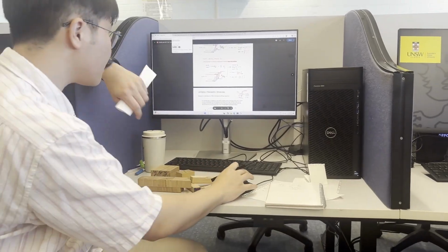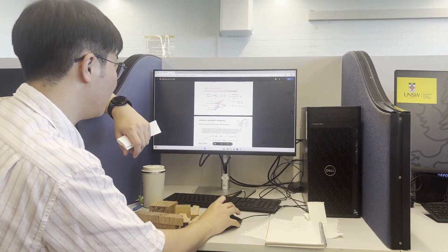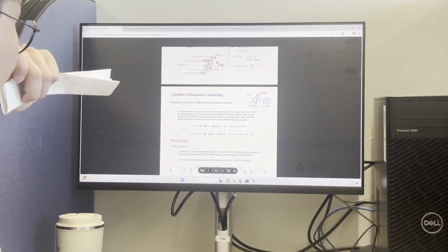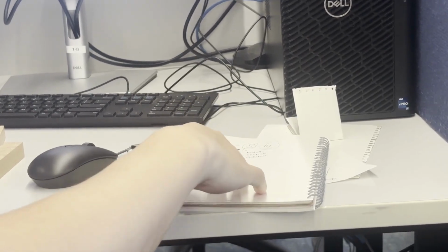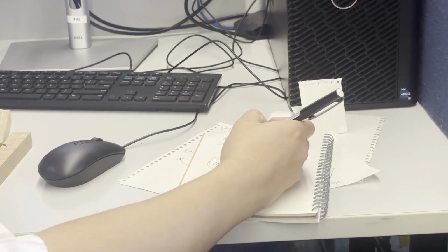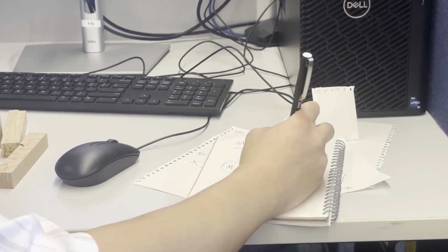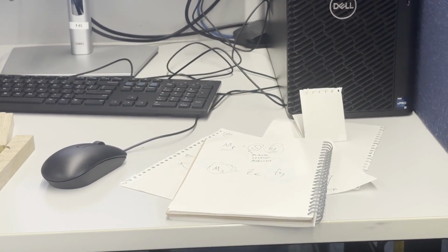Okay. So which one do we take when we're calculating the bending capacity in general? The answer is the section's bending capacity, right? Which was Ms, is something called Ze multiplied by fy. Okay.